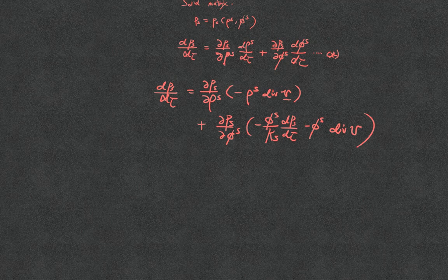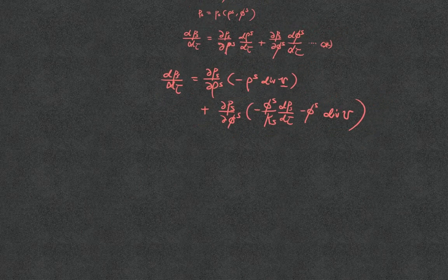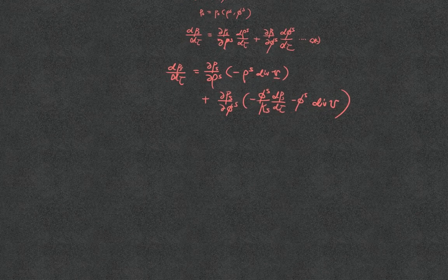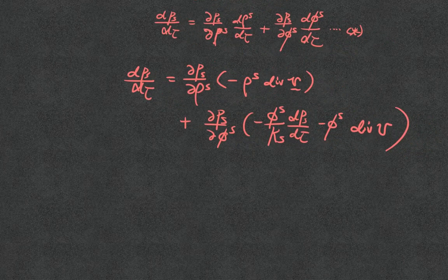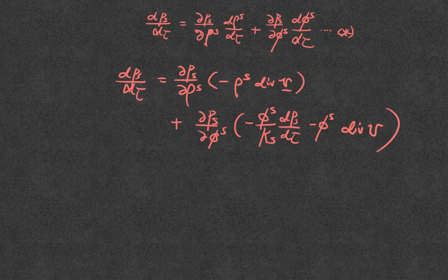Okay, so far so good. Now, just bear with me. I just want to derive the relationship between the intrinsic modulus and the bulk modulus of the solid matrix. So if you write out the previous equations, what we get for the bulk modulus is this term.